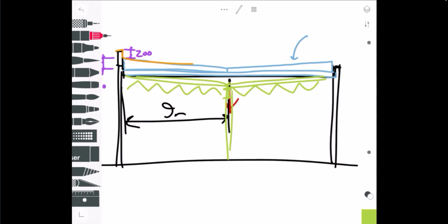A person could also consider, over the lifespan of the building, that having a sloped structure is kind of dummy proof as well. You are going to replace your roof over time. Would the people replacing the roof know, if you had a flat structure system, to do the tapered insulation or whatever?